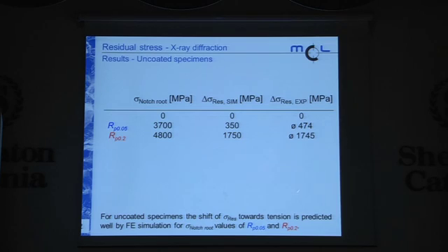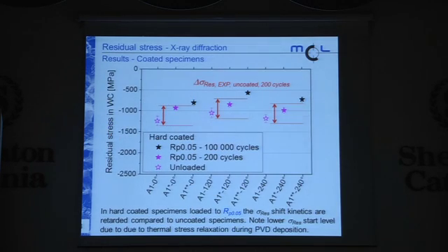And the differences are, with the small plastification, the differences between simulated and experimentally found values are, well, they're there, but the agreement was very good for the larger plastification value. So our material model works fine. This will come in very handy when we want to simulate real production processes and damage of production processes, say in fine blanking tools. Because in there, it's very important to know where residual stresses occur and what they will mean for damage for crack growth, as I showed you for the milling tool.